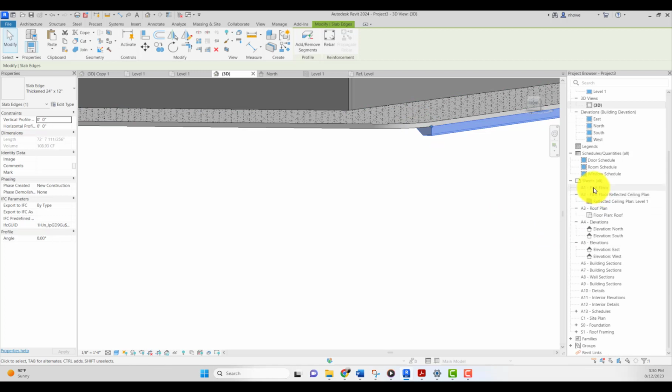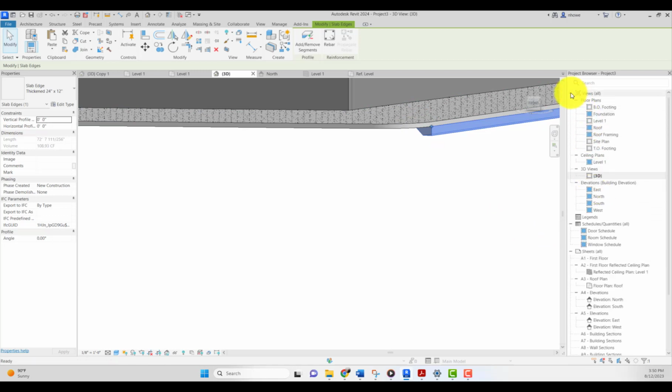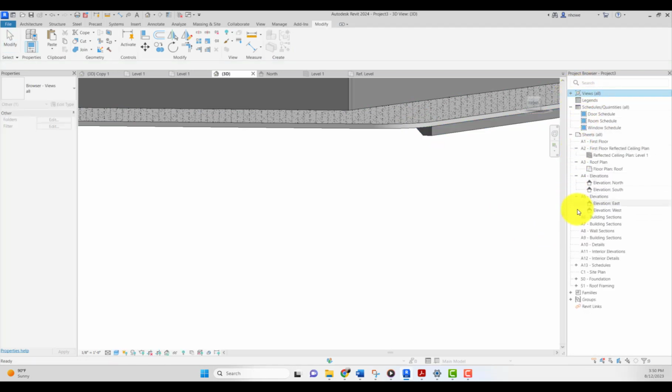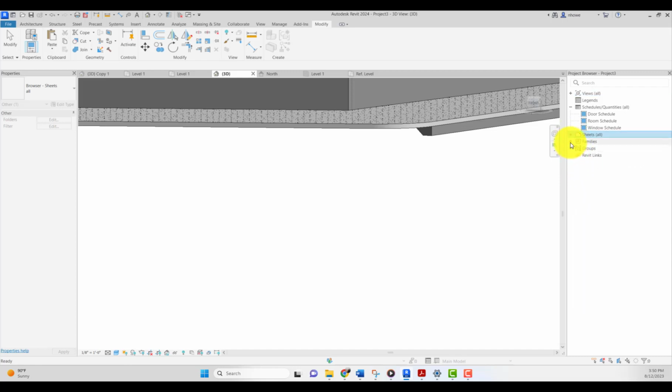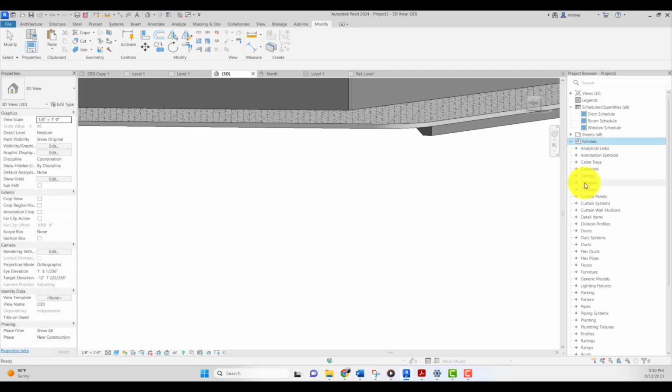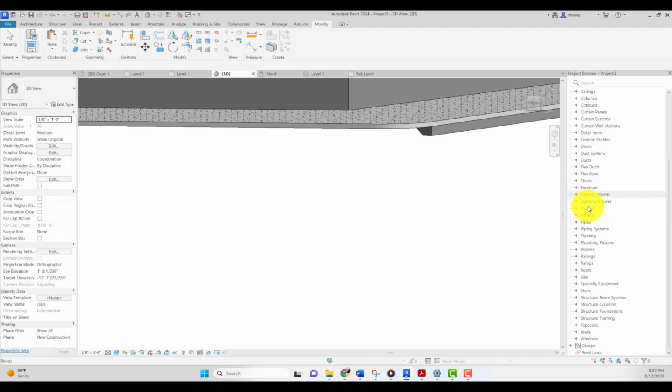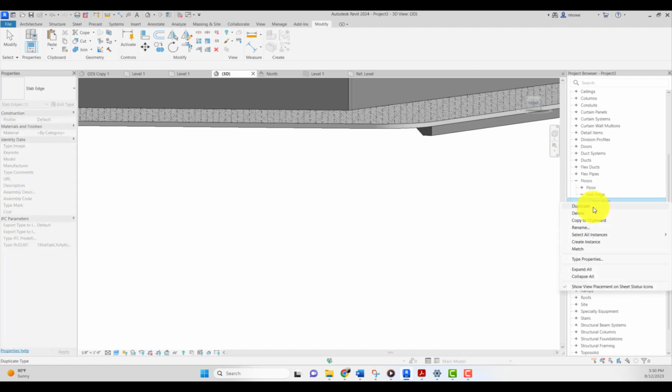So to do this, let's collapse the views. Let's collapse the sheets. Let's look at families. And we're going to go down until we see SlabEdge. We're just going to take one of these and duplicate it. And this one we're going to call curb.